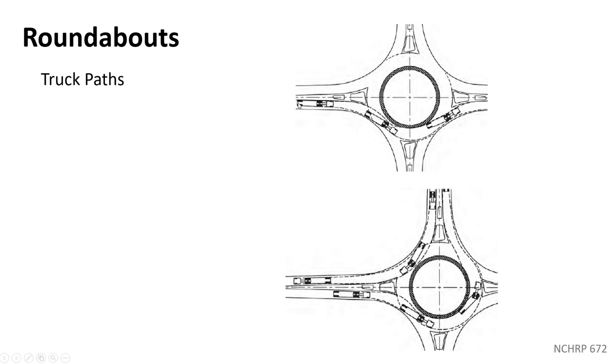So we talked about the fastest path. That's passenger cars, and it's probably 16-year-old kids with a sports car doing your fastest path through there. Trucks is a whole different issue. Remember that swept path, that's between the front tires and the last tires on the trailer. That usually defines our swept path, but it's these dotted lines in here through there, right? That's your swept path. So this whole area is being covered by wheels on the truck as it goes around, right? And you can see that it matches real closely.